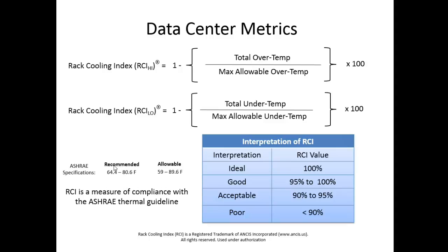In fact, many will argue you want to run 77 degrees or lower, because the fans inside these servers are becoming multi-speed, and they generally trigger to a higher flow rate at around 77 degrees. So you certainly don't want to be higher than 80, or you begin to defeat the purpose of reducing the supply air.